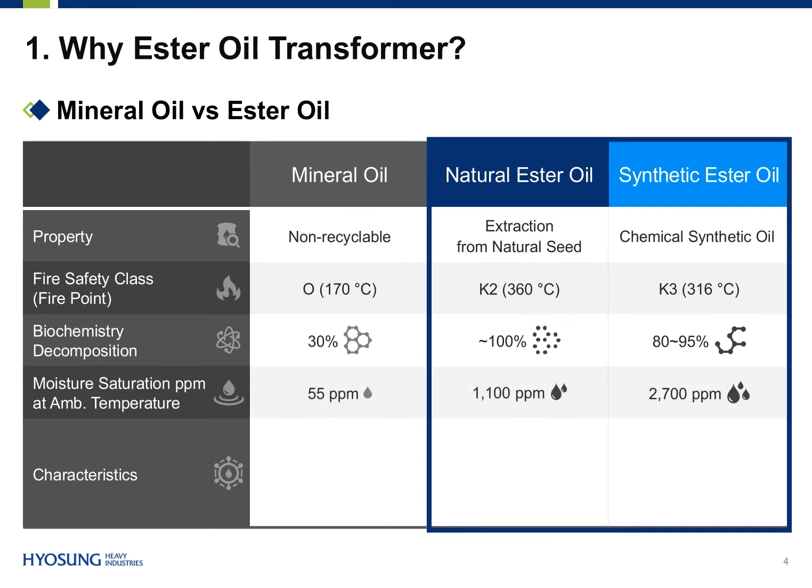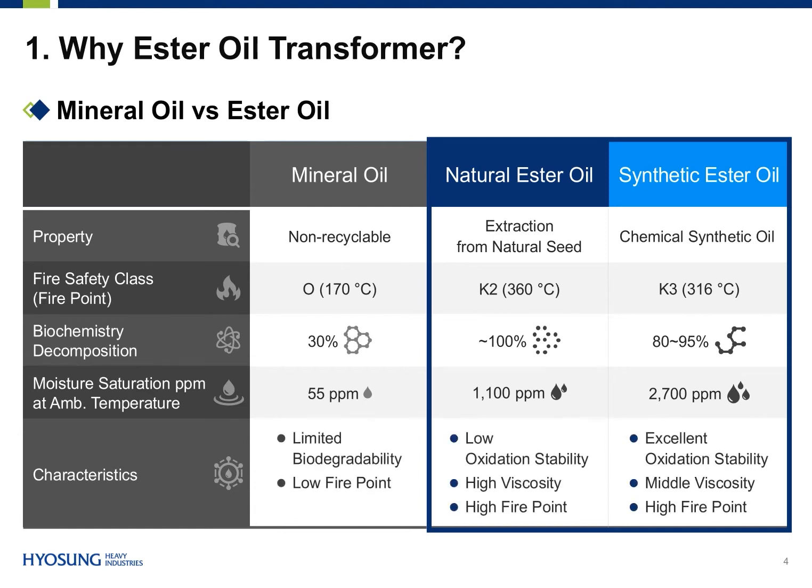Moreover, Ester Oil has a higher moisture saturation capacity than mineral oil. Therefore, the insulation material can have a longer service life. When comparing these two types of Ester Oil, synthetic Ester Oil has better oxidation stability than natural Ester Oil.